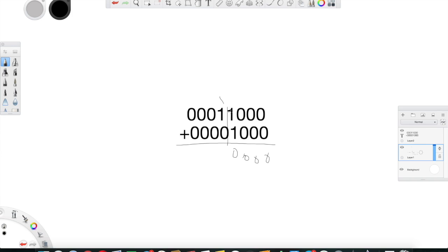The carry from bit 3 to 4, which is this one, will be stored in bit number 5 in the status register, which is the half carry bit. So if I have a carry from bit 3 to bit 4, this value will be stored in the half carry flag. Therefore the half carry flag will have 1 in this case, because 1 plus 1 is 0, carry 1.